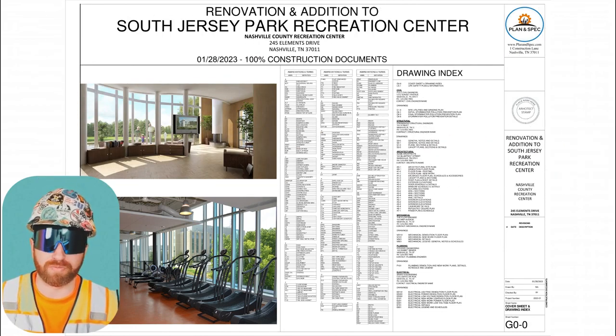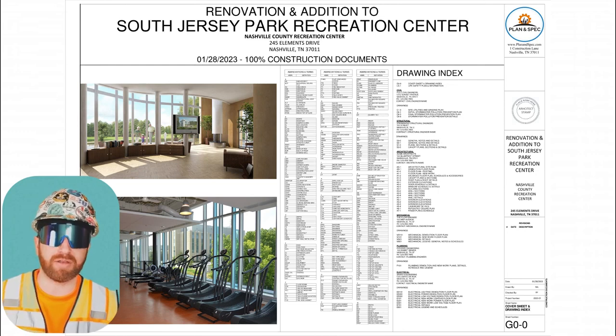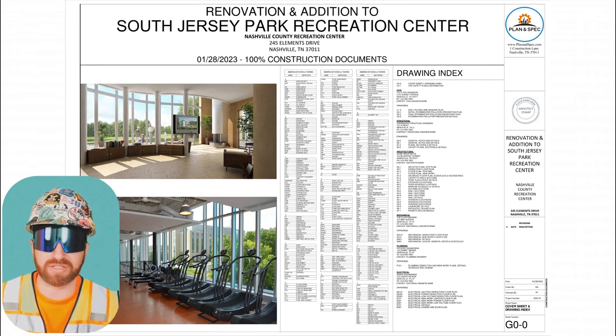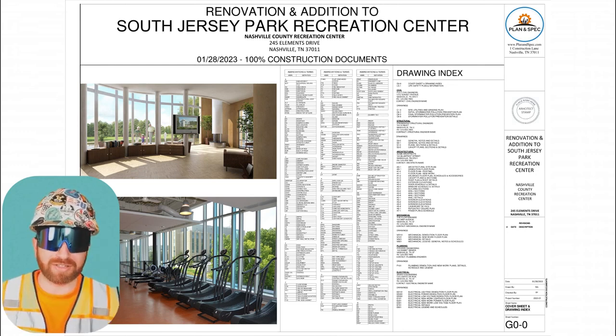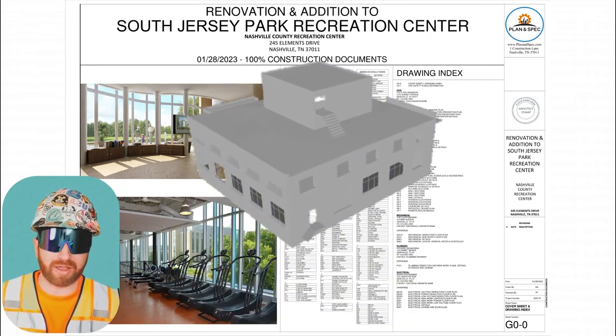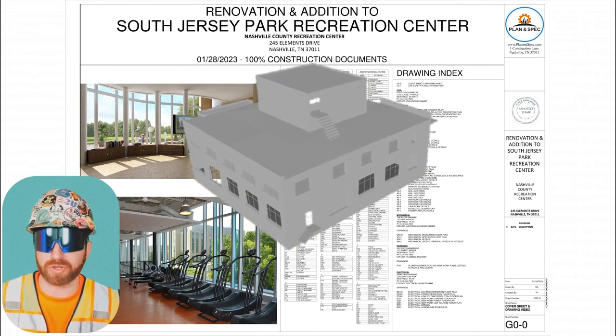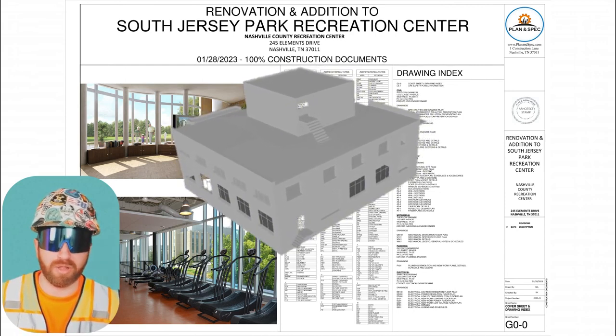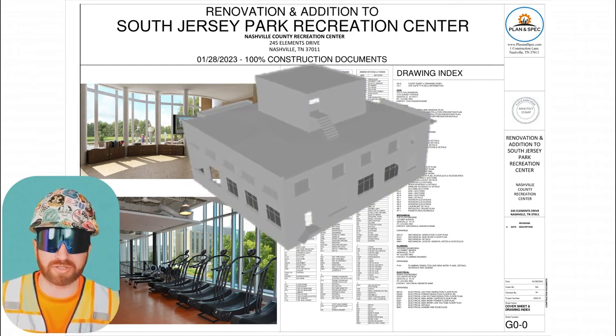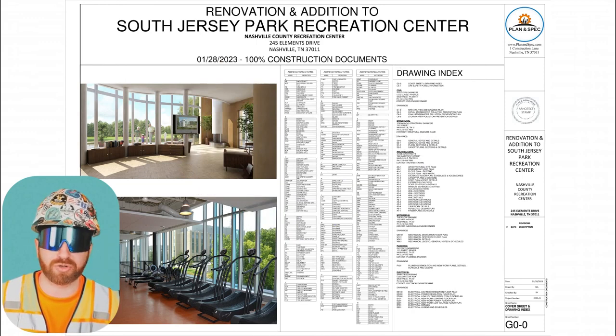After I complete a general review of the disciplines, I then do a second pass where I further dive into these disciplines individually. If the architect can provide a model of the building, I'd highly suggest that you ask for that. That way you can have two monitors going, one with the drawing set and one with the building model. This will help you more easily digest the drawings and the project in general as you're going through these pages.